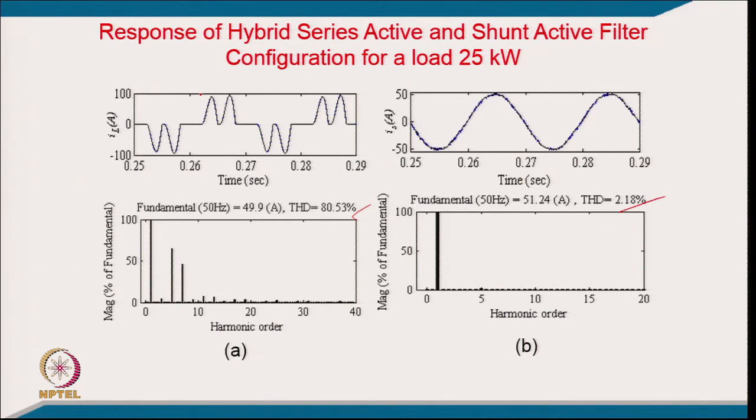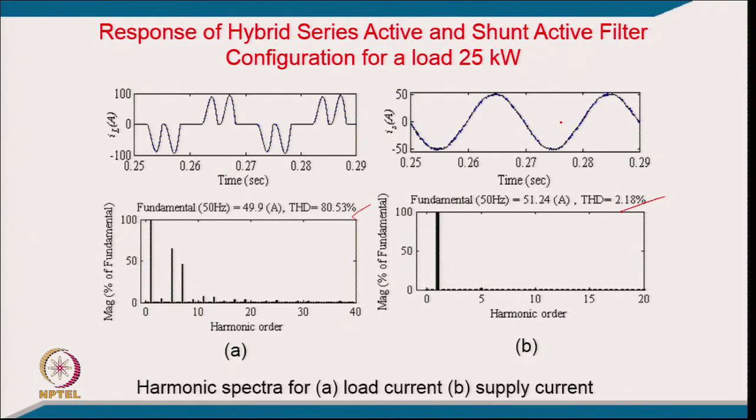So, it means the high order harmonics and the high crest factor are also reduced, typically here from 80 to the order of 50. So, that makes a big difference, in that the peaky current is also avoided, not only the harmonic current, especially in the case of a voltage fed kind of load.